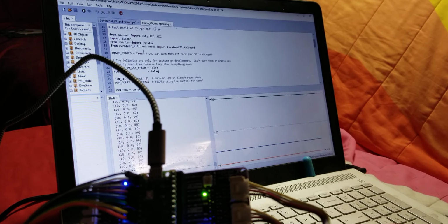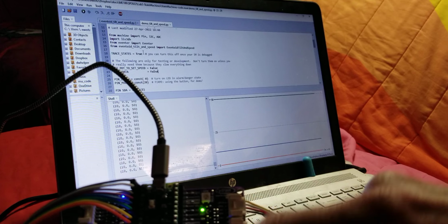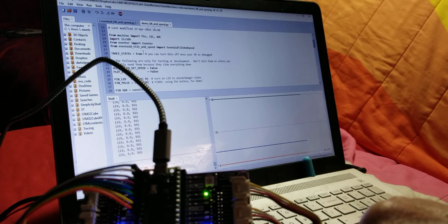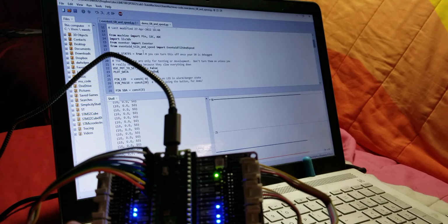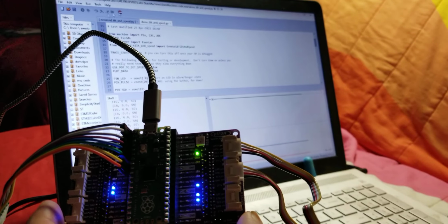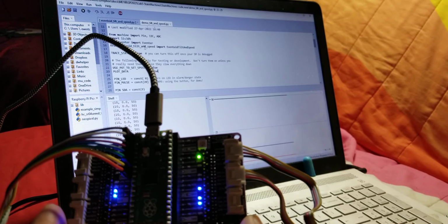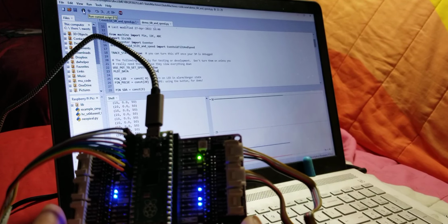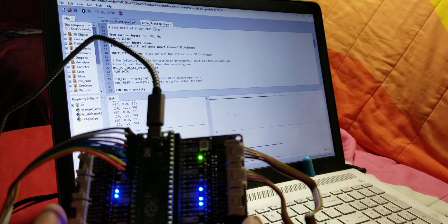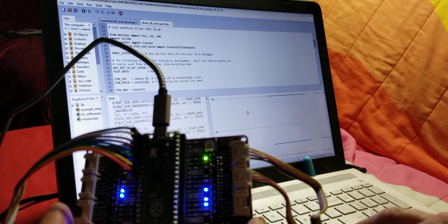And I've got to warn you, because this program uses interrupts, almost every time you stop the program, you have to reset the processor by pressing the reset button on the baseboard. And then hitting stop to reconnect, and then hitting play again. So now this turns off essentially the live plotting, so that now you can just see the event messages.